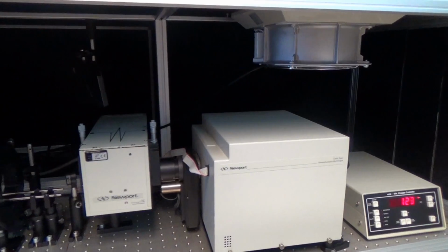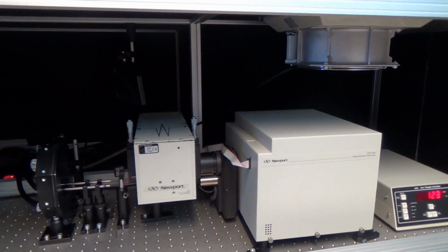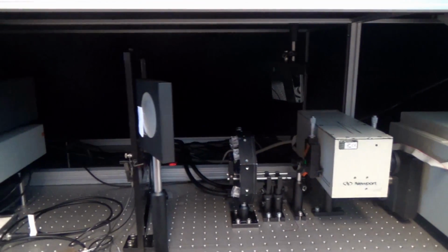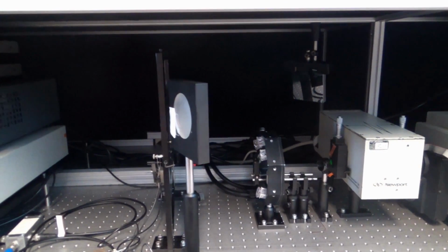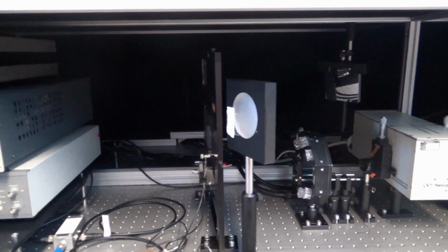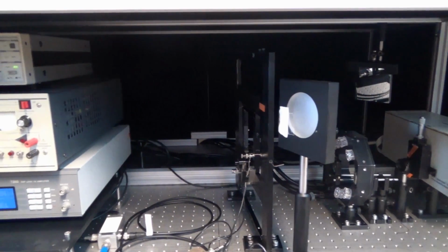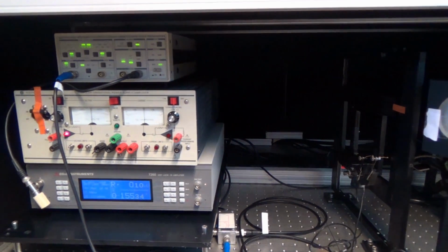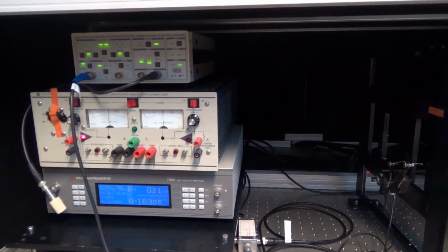We will now look at a lab-scale EQE measurement setup and demonstrate how a sample is correctly measured. Here we see an overview of the setup, starting with the chopper frequency generator, the light source, the monochromator, a lens system and a bias LED ring, a mounting frame for the sample, a lock-in amplifier and the power supply.